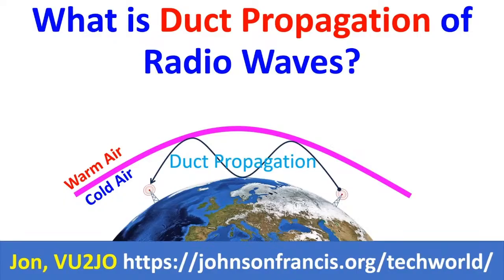This leads to refraction of higher frequencies down to Earth instead of going up into the ionosphere. Reflection from the ground back to the troposphere initiates a similar process again. This has been called duct propagation or super refraction.